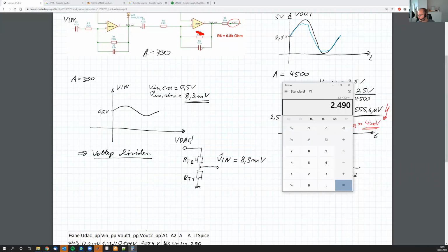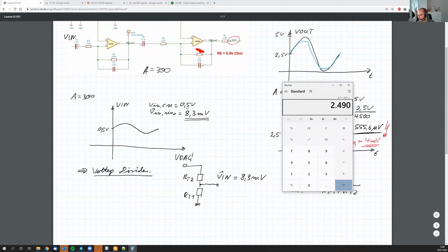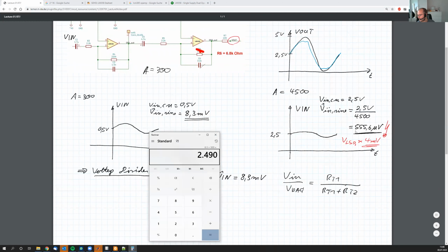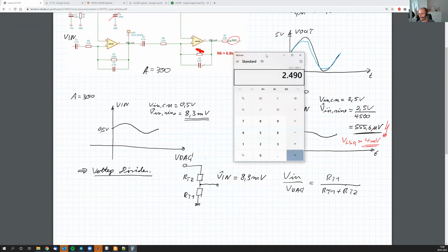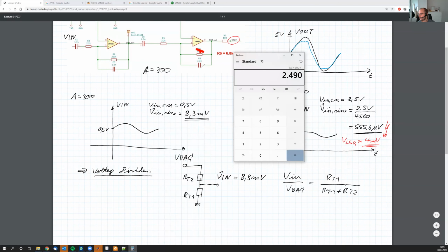Now, you have to calculate a little bit based on that. So you want to achieve a common mode voltage of 0.5, and that as a swing. And if you have the 40, I'll leave that up to you. There are not too many possibilities what to do with those numbers now, okay? Yeah. So, and this is how you can calculate your voltage divider.